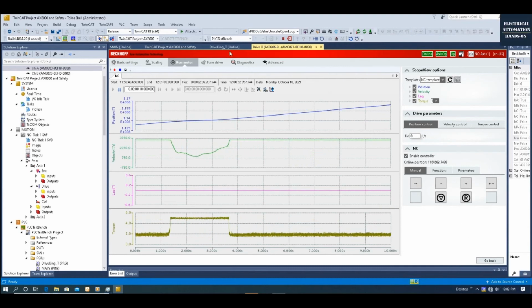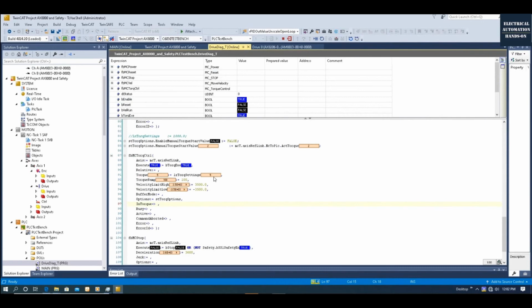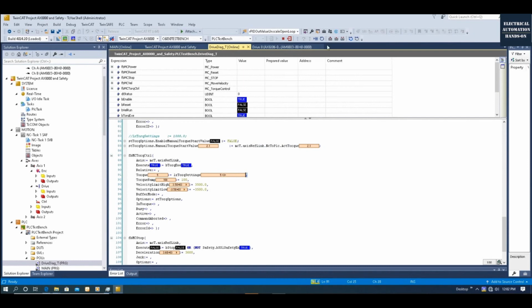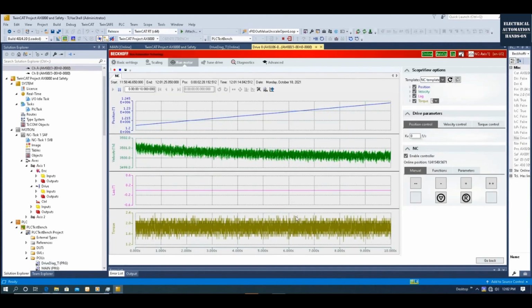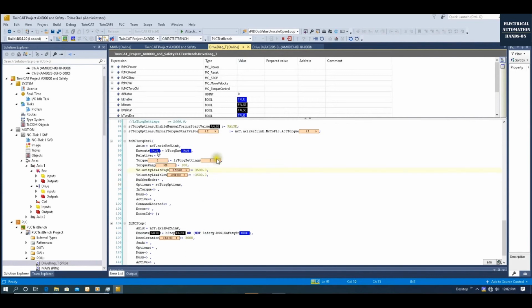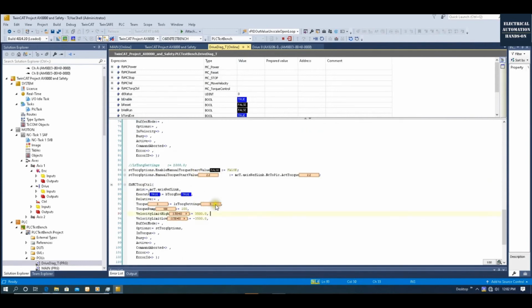Alright, now let's shift to the topic: how can we use two instant function blocks to update the torque setting. If we switch to 3, currently I'm still using one instant function block so far. If I use the same instant function block, the 3 won't be updated. Apply the same load, and we can see it's still running at 5%. To implement this set point update, we have to use two instant function blocks here.